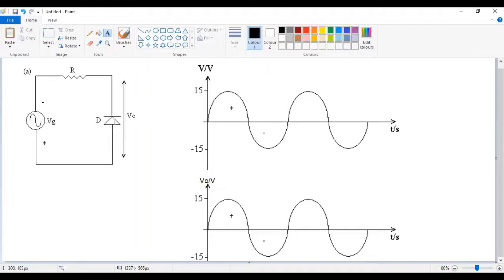So if it is short circuited, the voltage across a short circuit is simply 0. It means you would not have this segment there. This segment would not appear because the voltage would not appear. So this is what you expect to get at your output if you have such a circuit. You can see here clearly you're maintaining all the positive half cycles. This is called half-wave rectification.